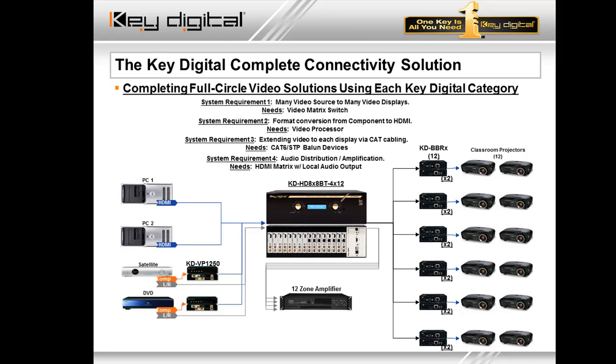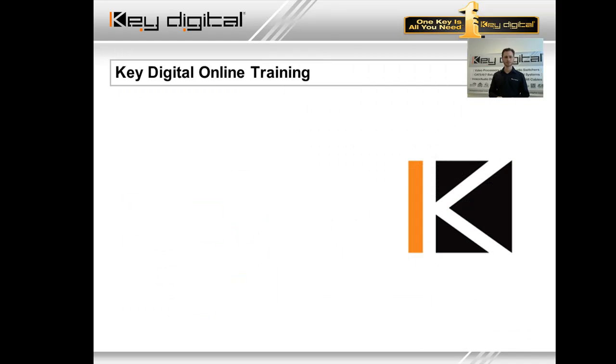I always forget to talk about this, but because the Hercules and Digital IQ series features RCA output connections, this is a great way to take advantage here. Use those left and right RCA outs and feed into your 12-zone amplifier, as we can see here. And now you don't need an extra audio switching device or preamp, etc., because we got the volume control, multi-band EQ, even lip sync delay that can be added through the Hercules and Digital IQ series product.